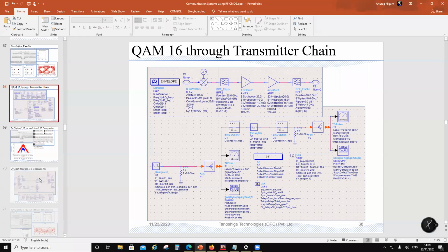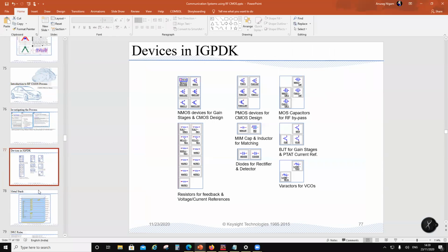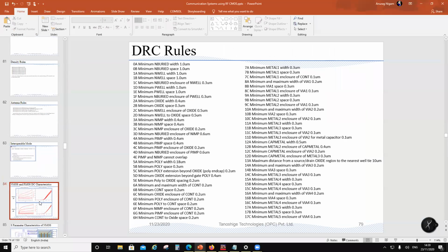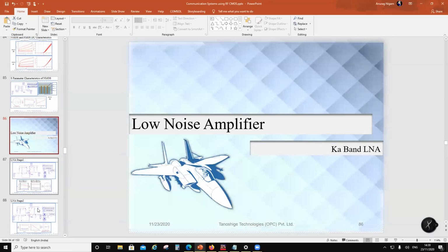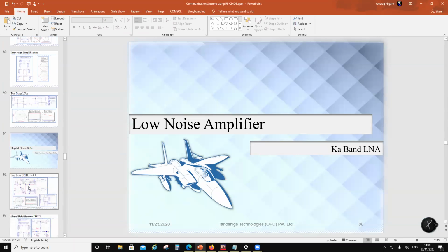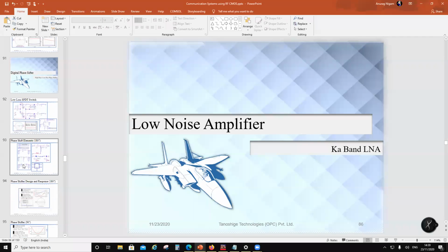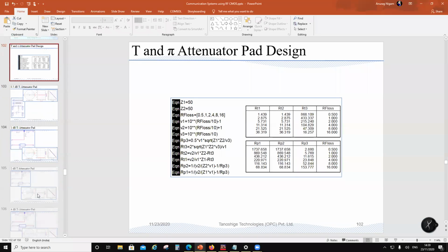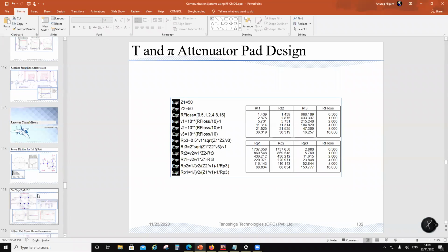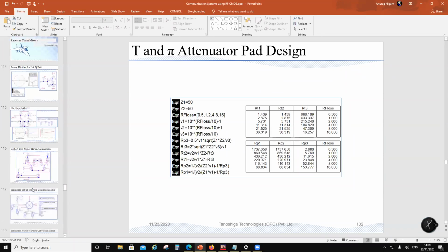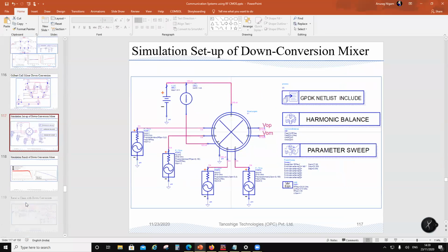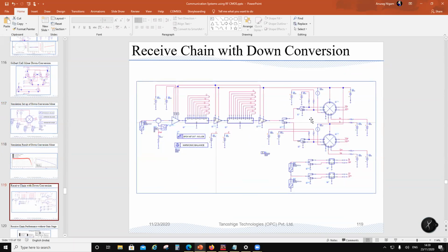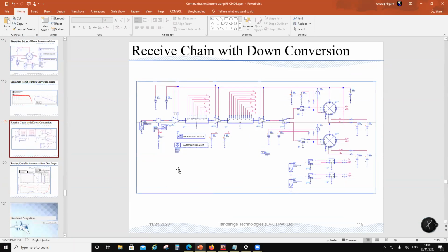And after that, I will go into a process and I'll start making these blocks, starting with LNA, PA. I will not cover switch. I'll cover switch, but from a different perspective. And then I will do what is called digital phase shifters and attenuators, 5-bit, 6-bit. Then I will start putting the chain together, transmit and receive chain. I'll do the mixers, VCOs, and I'll start putting the chain together. So this is like the receive chain, right?